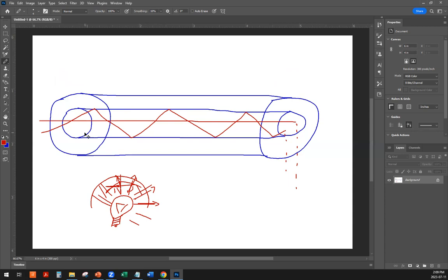Now, to resolve this issue, somebody smart got together with somebody else who is also smart, and they came up with a great idea. Let's say the index of refraction was not a clean cut from one place to another, but towards the center the number would be the greatest, and the core would have a graded index of refraction towards the cladding. So the index of refraction would just decrease, right? Not increase, but decrease towards being a smaller number as you go outward from the middle. The index would go down, the number would go down. Okay. What does that accomplish?